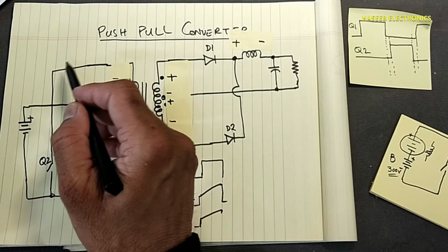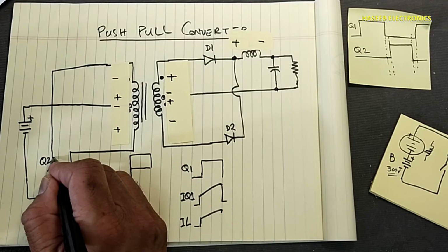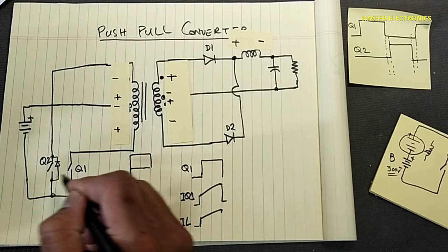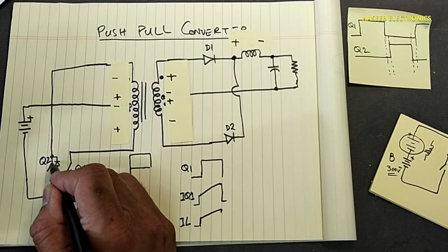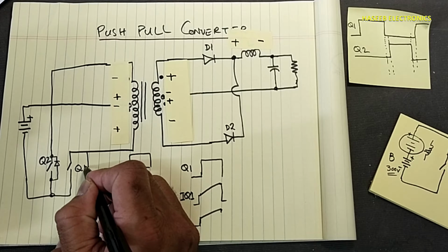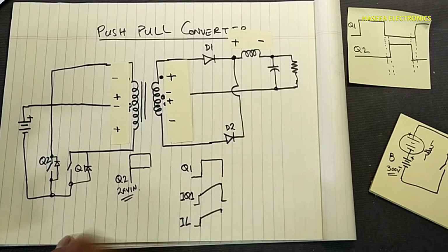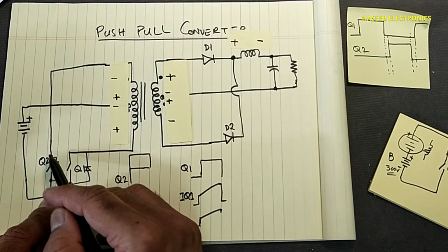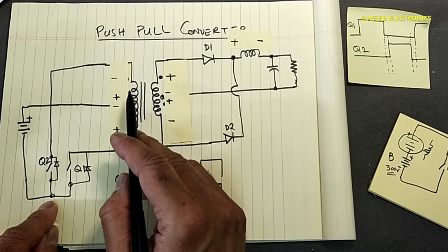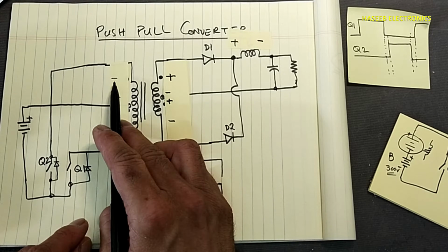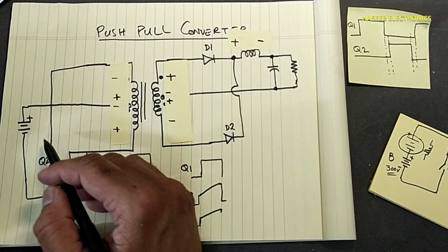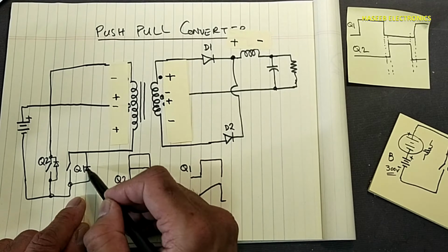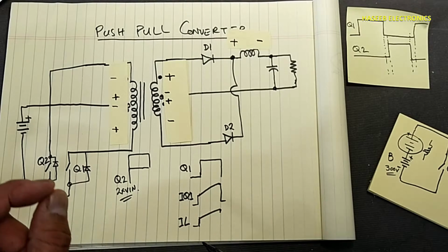When this end is negative, in parallel with both switches we have recovery diodes with Q2 and with Q1. Now this negative side is reaching the cathode. It will discharge and demagnetize the core, because the voltage produced will take the easiest path to ground. And if we see this diode, this is now reverse biased and this transistor is now open.